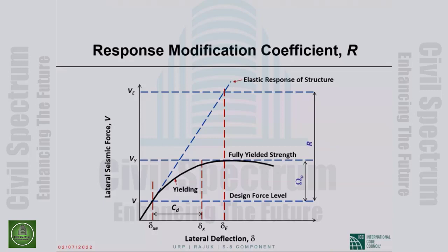Simplest way of looking at it is the ratio between the hypothetical elastic design base shear and the design base shear we are actually using in design. Okay.